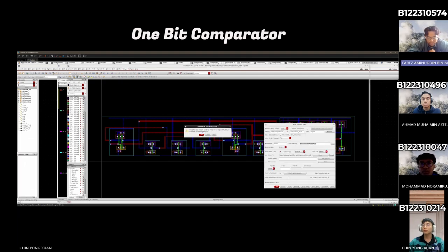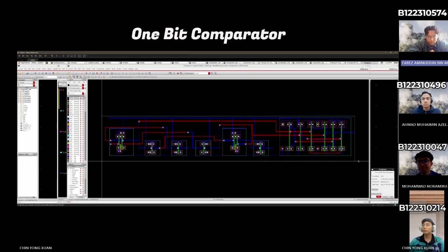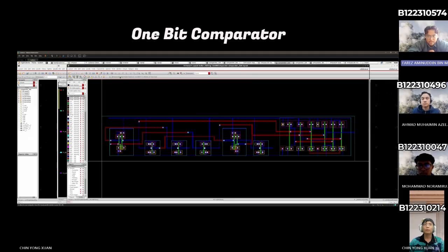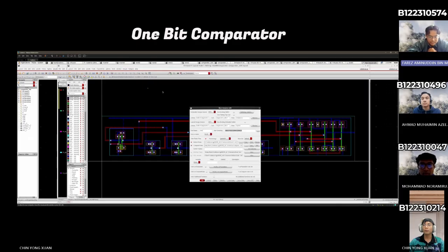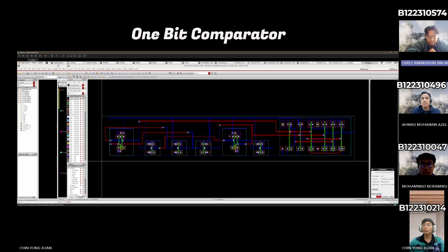Design rule check acts as our automated physical enforcer. It systematically scans our geometric drawings to make sure they strictly obey the foundry's manufacturing limits, checking critical parameters like minimum wire width, exact layout spacing distance, and area constraints for the 90 nanometer process library. We were happy to report that our design successfully cleared this stage, returning a clean, no DRC errors found notification window. Next up was the layout versus schematic check.